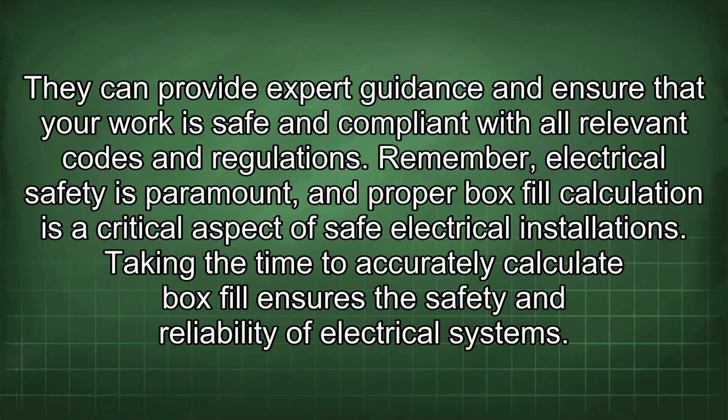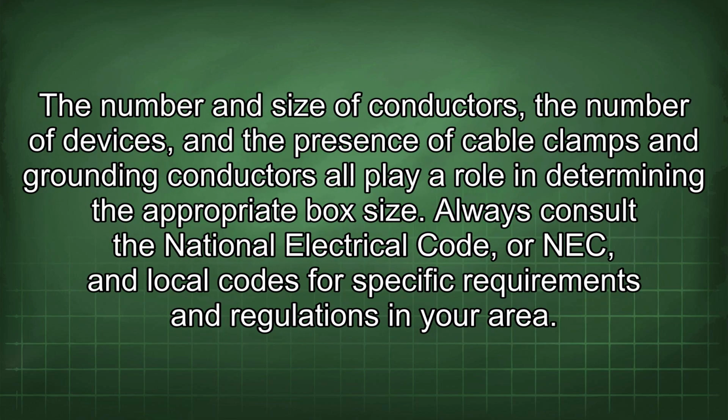Taking the time to accurately calculate box fill ensures the safety and reliability of electrical systems. The number and size of conductors, the number of devices, and the presence of cable clamps and grounding conductors all play a role in determining the appropriate box size. Always consult the National Electrical Code, or NEC, and local codes for specific requirements and regulations in your area.